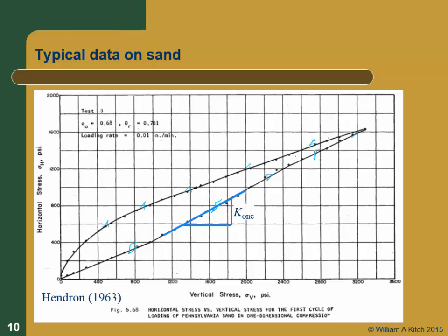What's a normally consolidated soil? That's a soil that's now at the highest stress it's ever seen. So during loading, the soil has to be normally consolidated. These are artificial specimens. He placed sand in these at different densities, and then started loading them. Okay, everybody with me? Questions? So that's K naught NC.